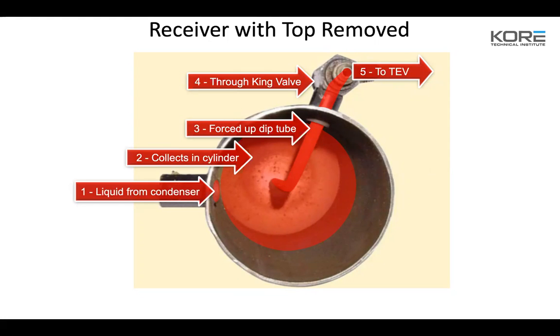well, if we didn't have a receiver on there, then it would be starving on the one side of it. And it would cause it not to create enough superheat or boil off enough refrigerant or flood the coil enough to get the heat transfer you need for the sizing. So we have to put these receivers in there to make sure that we keep that liquid on the backside of that expansion valve. So the other thing too is, has anybody not snap torched a receiver?